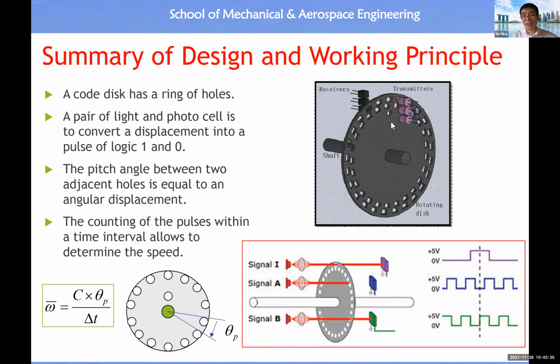And this one is for us to know what the 0 position is. If, let's say, we start from a 0 position to do the integration of accumulated displacement, the result is what? The absolute position with respect to the 0 position. All right, so now you already have an overview about the working principle of this velocity sensor and the key element inside the design of the velocity sensor.